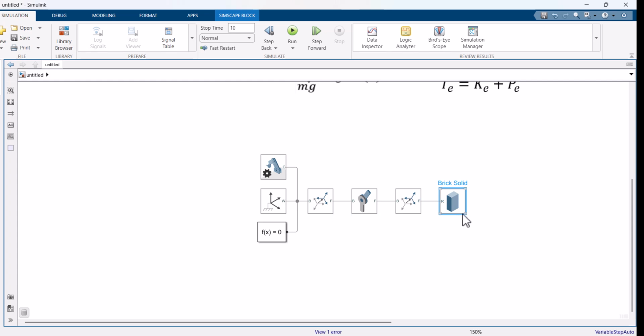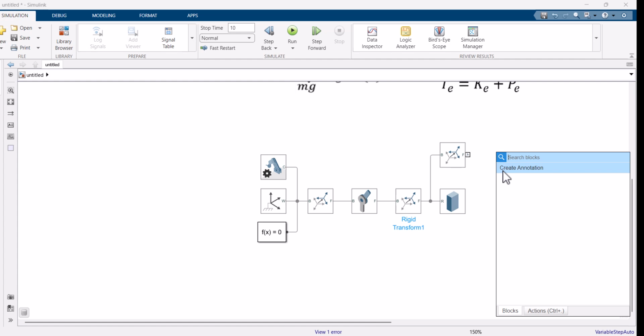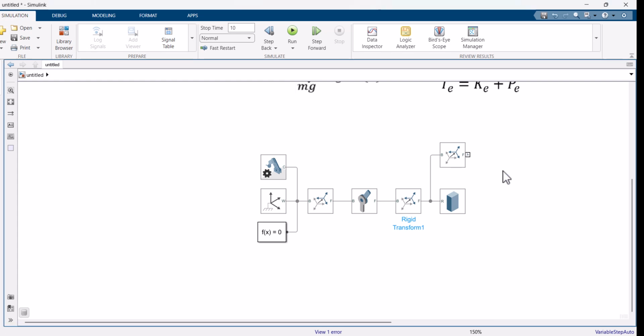and at the end of the rod, we want to attach the pendulum bob. Now to go to the end of the rod, we can use this transformation once again. And now this F part, the follower part, has moved L by 2 downwards again. So now we will be at the end of the rod. And over here, I can attach a spherical solid. This will represent our pendulum bob.